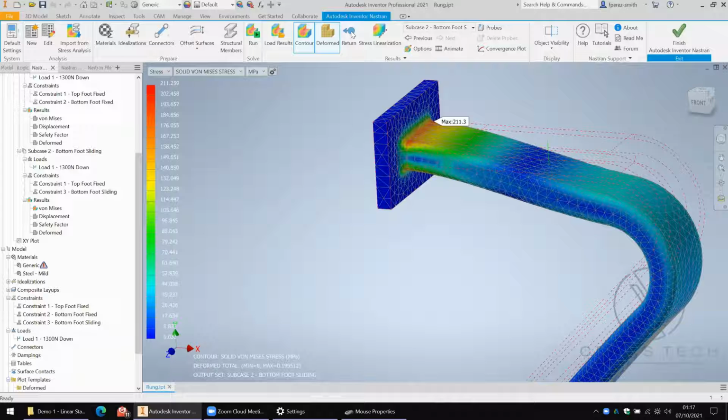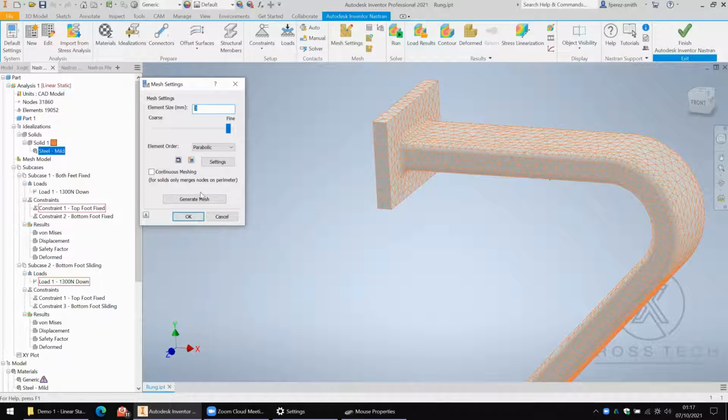So we'll click return. Rather than refining the global mesh, we could come along here and say 0.0001 and be here all century to calculate, but let's be a little bit more clever about it. We'll do a local mesh refinement. So we'll come here to mesh control, and here we can choose vertices, faces, and edges and do local refinements of the mesh.